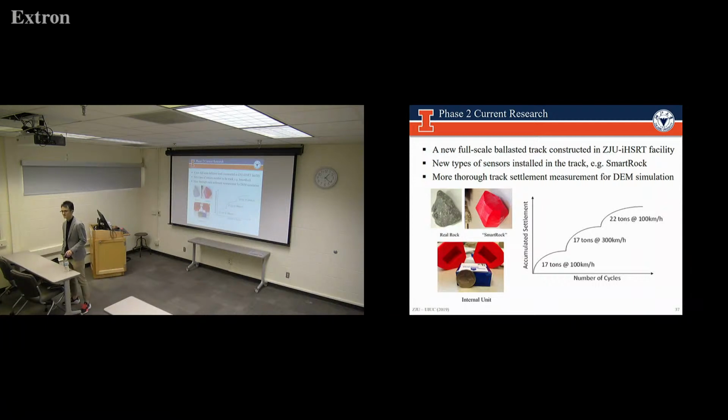Since ballast is mostly one-size particles, if it's compacted to the maximum, but we don't know the density. But if we can know it's compacted to the maximum, then we can find out the density by lab measurements, because you can do lab measurements to get rodded unit weights. We do it for our mixes.